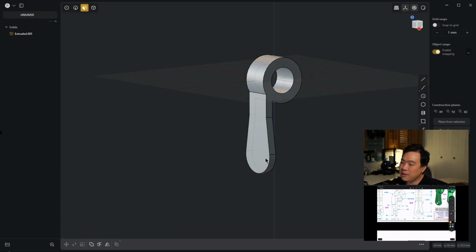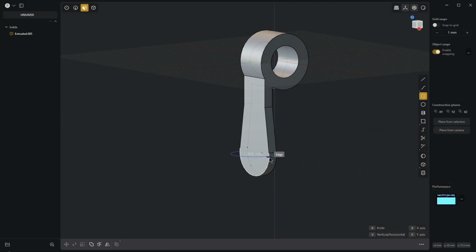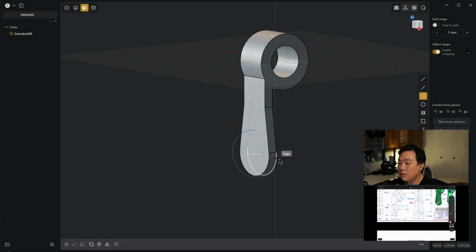Moving on, from this tail, we're going to create that cylinder that sticks out, and then we're going to create a hole that punches through everything. So here I'm going to activate the center circle tool again, and click right on the center over here. Notice how right now it's not in the orientation that I want, but on the bottom right corner, it shows the hotkey to switch between vertical and horizontal, and that key is V. So I'm going to press V once, and it switches to the correct orientation.